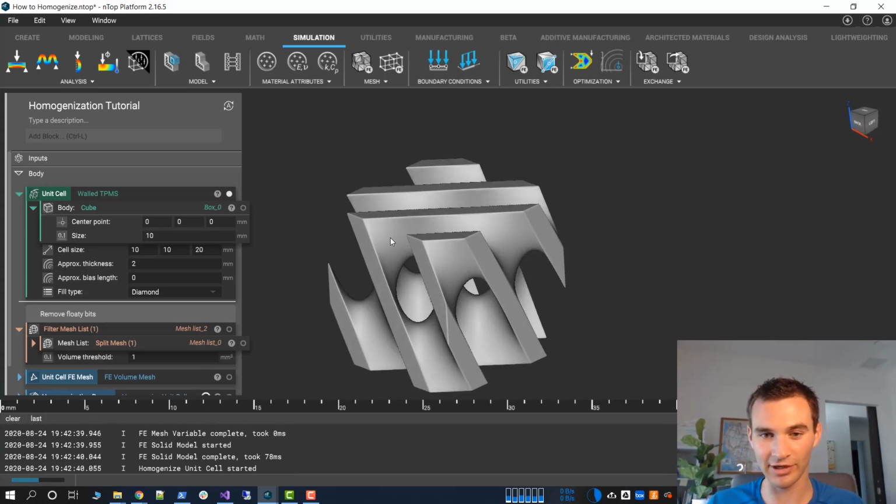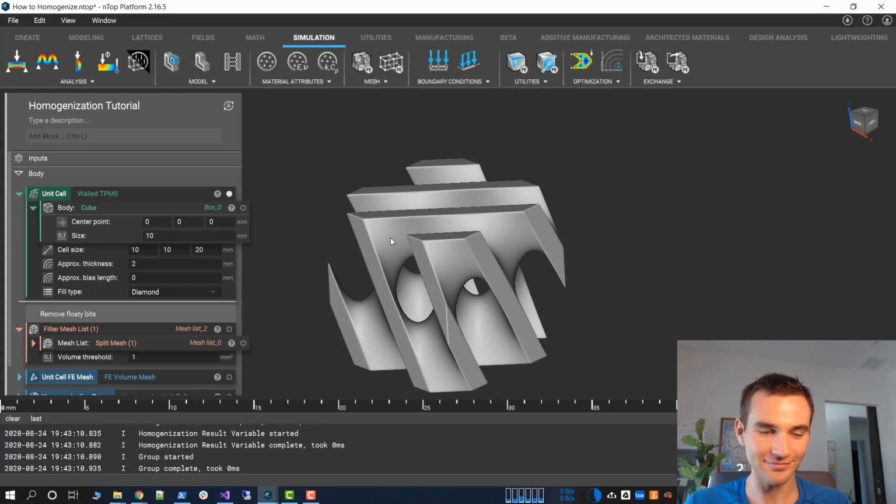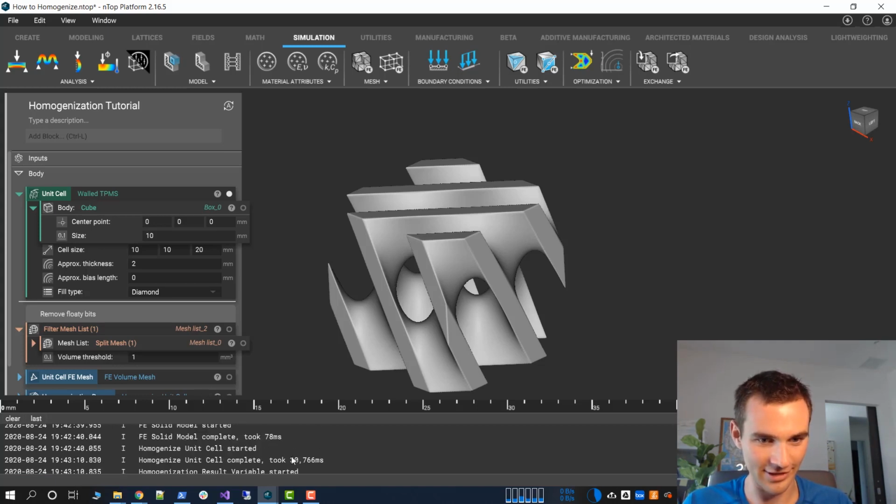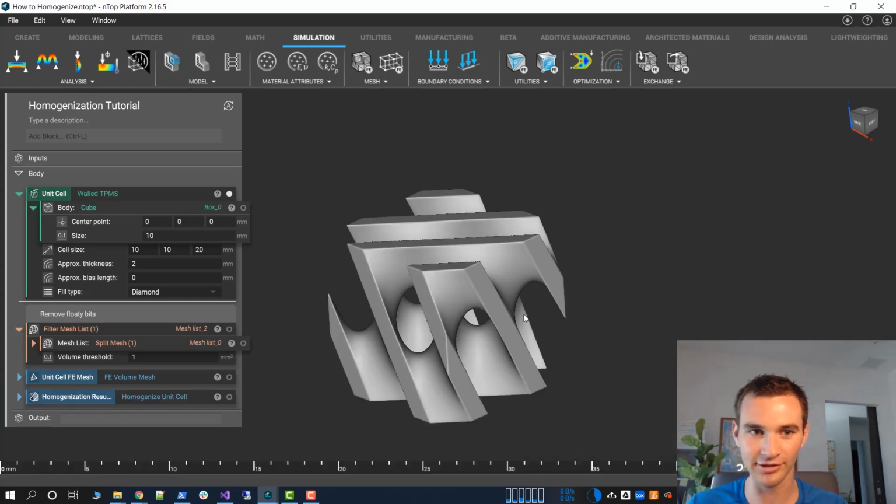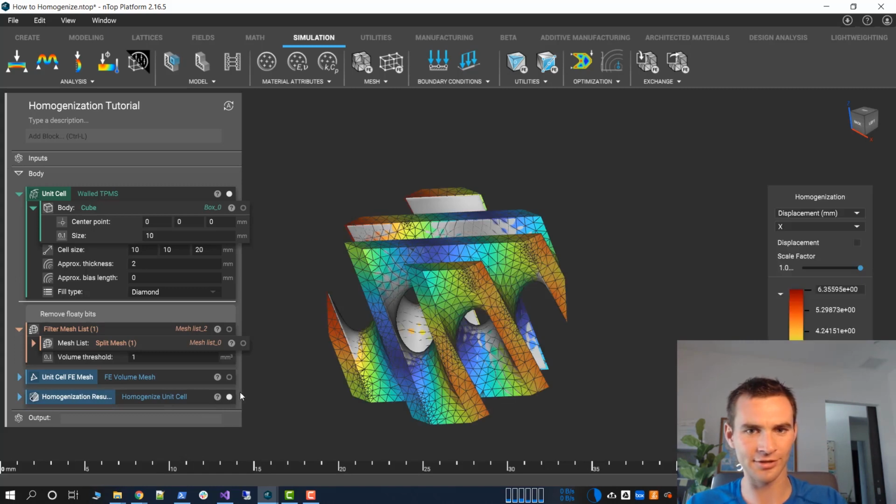What's nice is that some of our users have actually linked this up through our batch processing. So they list out a bunch of different configurations and power through them through a script. That's a different how-to video, though. Okay, how long did that take? So with meshing, 35 to 40 seconds, pretty good to get you a quick answer.